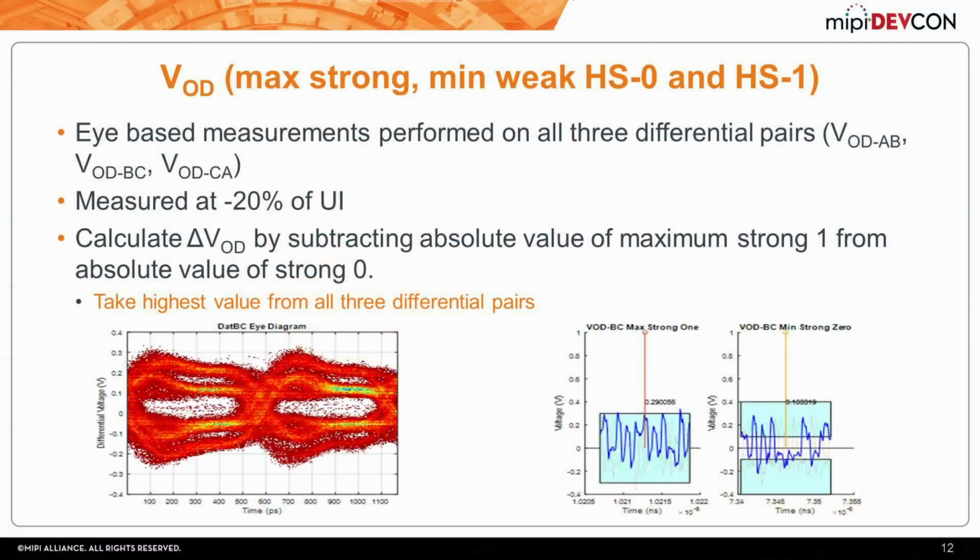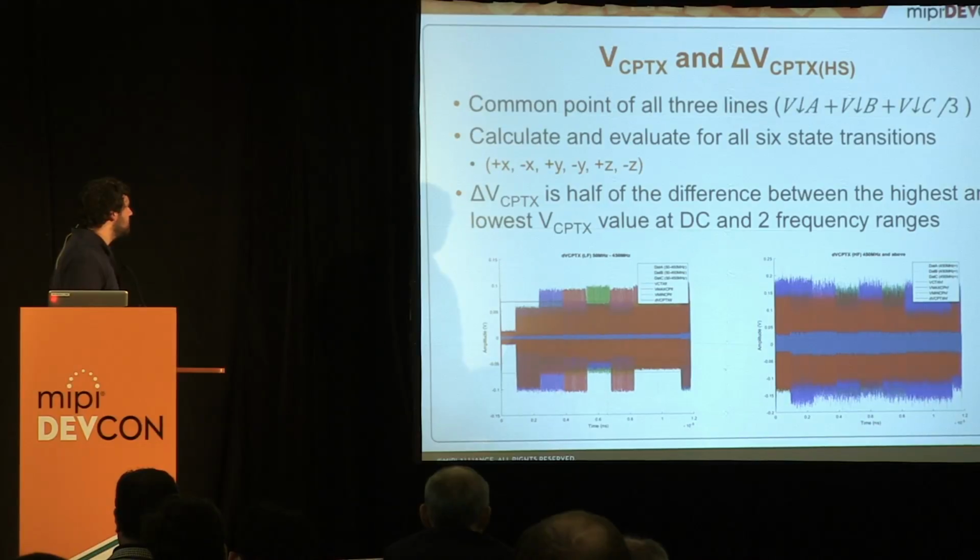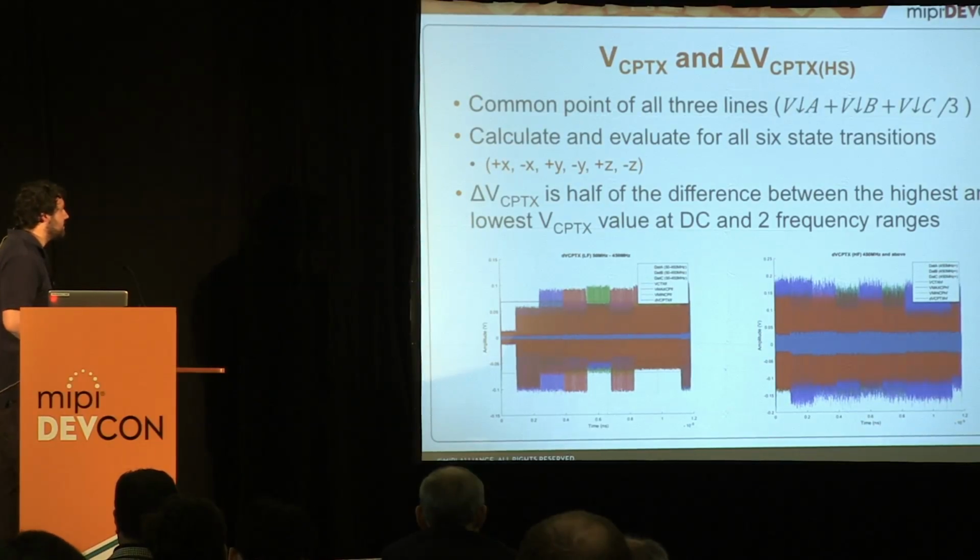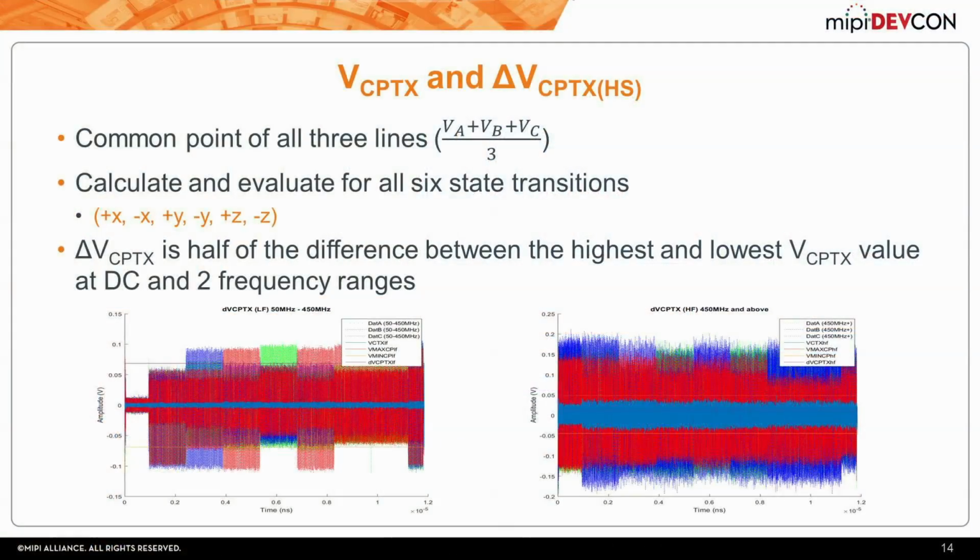And in case I didn't mention this earlier, on this slide, when you're doing VOD, you're doing all 4 of these measurements for all 3 differential pairs. So this, I think, was probably one of the more interesting slides. It's the common point tests.